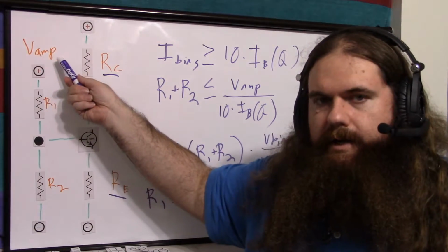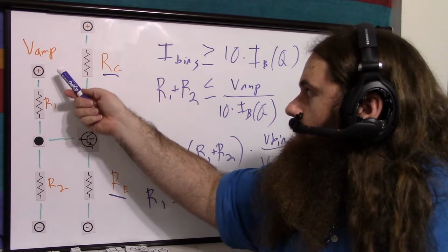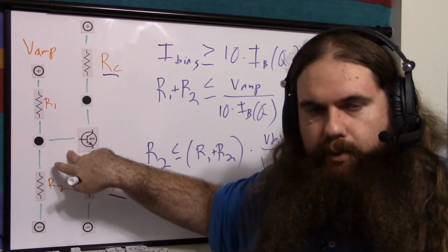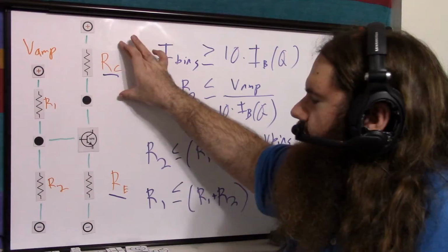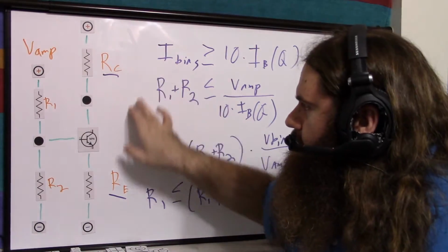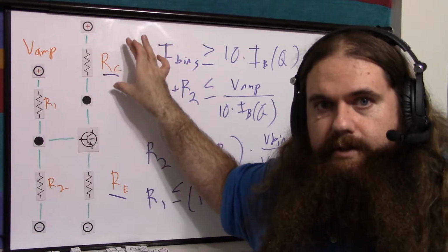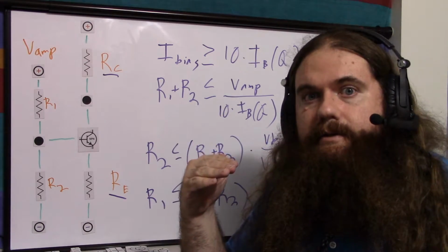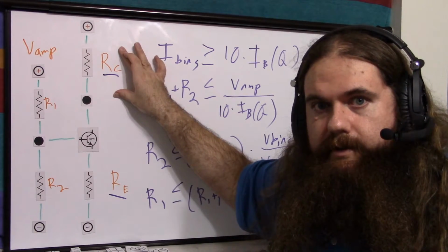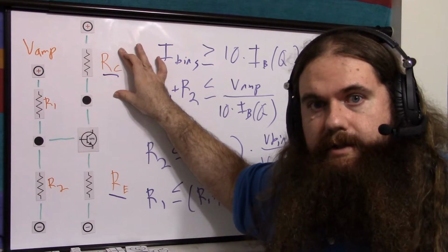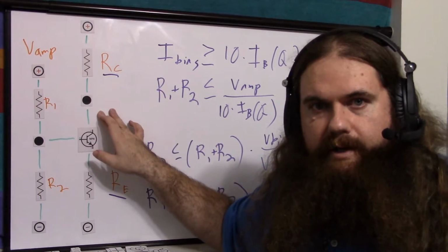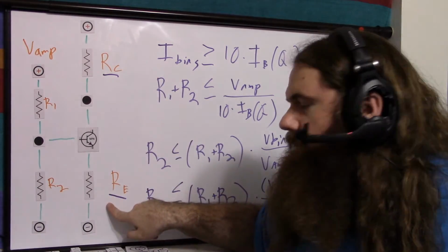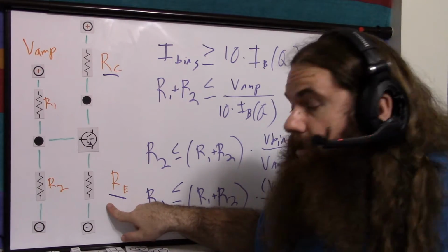And that's it. You decide on the voltage you have from your wall. You decide on your voltage across RE at quiescence, your safety margin. Decide on the 0.7 volts here. Then you calculate how much voltage can go over here, which is the total but a half. You use a power target, deciding how much power you want running through here when there's no signal or the signal is silent. Calculate a current from that power and this voltage. Calculate the resistance from that current and this voltage. Use your beta, which you decide is probably 100, to calculate the base current from the collector current. Use the combined current with the voltage here at quiescence to decide on this resistor.